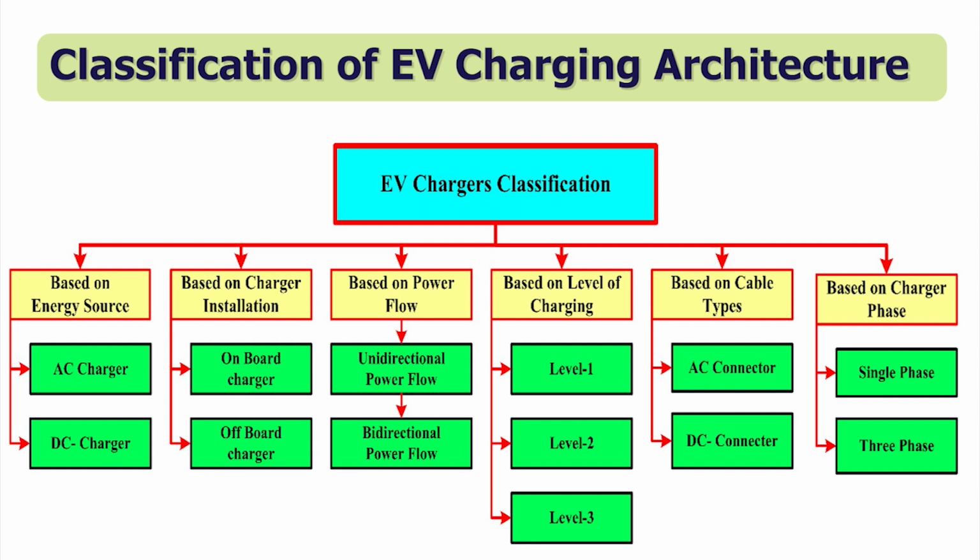Here we have another topology for EV charging station, known as 3 phase 4 wire. Whenever there is a problem of neutral current, we need to compensate this neutral current when there is unbalancing from the charging side, because we are considering the battery as a load and we need to supply some power to these batteries. So, we need to take care of the neutral current and its magnitude should be mitigated. For that purpose we can utilize this 3 phase 4 wire topology.